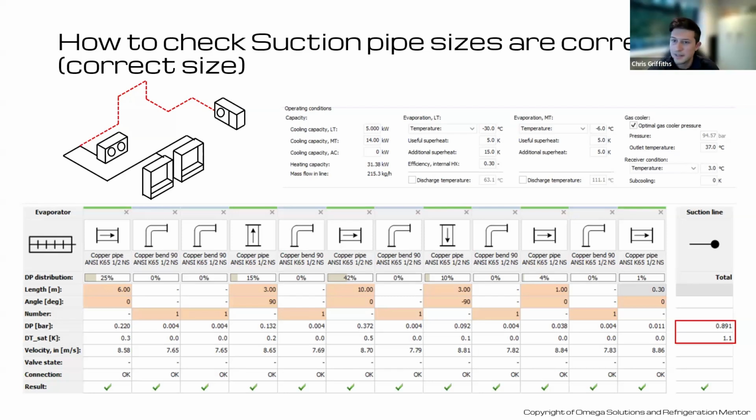As you say, Trevor, the stuff which we used to rely on for HFC, most of it can still apply for pipe sizing, you just get smaller sizes. But as you just said, different technologies and different components are coming into play, and it does mess with your rules of thumb slightly. Yeah, and then you've got to size accordingly to that, because you might have the best pipe sizing, but if you make a mistake on that plate heat exchanger or something that's going in there, that's going to mess up your pressure drop. So, or components. Yeah.